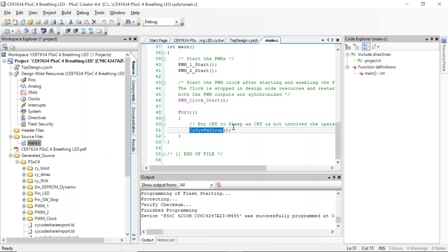The power in a CMOS chip is equal to an activity factor times the frequency times the capacitance that's being charged and discharged times the power supply squared. And so if you can change the activity factor to 0, well, you won't use any power. So that's why I think PSoC has a real advantage, is that it can completely turn off the CPU and still do other things. And that's it.